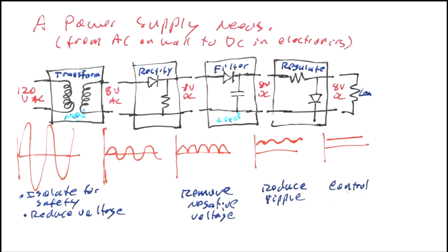Something else about, oh, so there are cases where we don't expect to have any access to the high voltage AC. So light bulbs, LEDs that plug into that socket, you're not expected to be able to touch the line and neutral on that. And so those don't actually have to have isolation. So something that plugs into it and it's supposed to be plugged into, it's not going into a wall outlet, it's going into a light socket or some fixture like that.